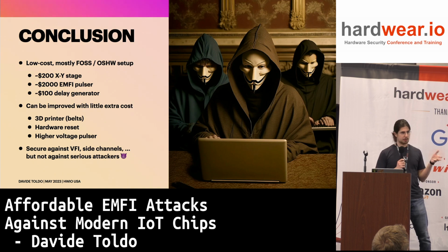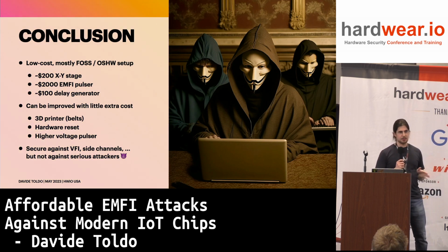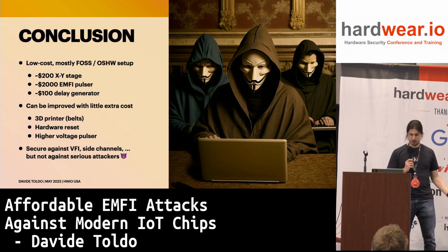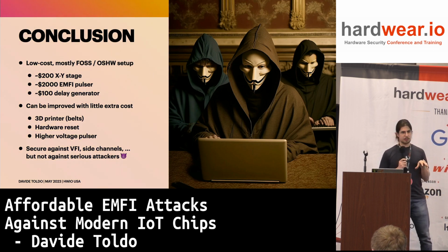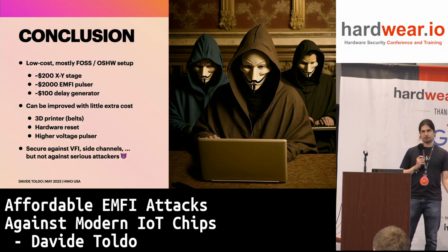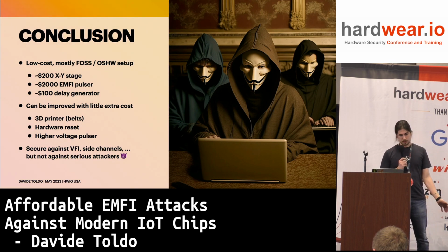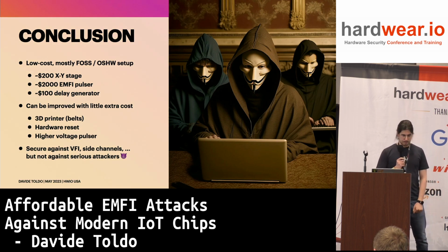Use a proper hardware reset that is reliable. You don't want it to reset your target when it shouldn't. And maybe you might need a higher voltage pulse. I spoke about the PQMP. I haven't tried it on this target, but it doesn't go as high with the voltage. And I did need the almost 500 volts from the chip shorter on this target. If you don't get the results you expect, maybe try higher voltages or a device that goes to higher voltages.